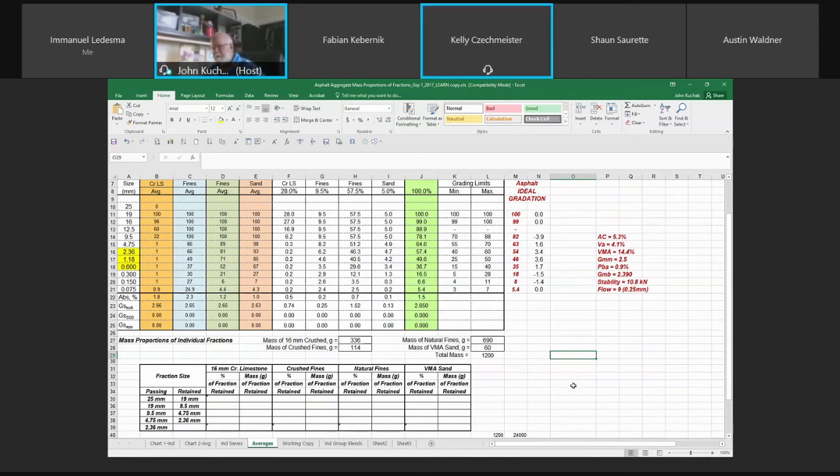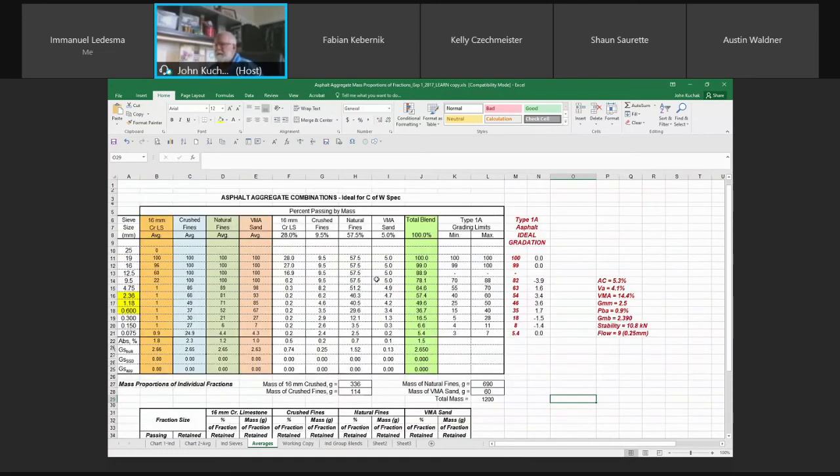Anyway, so it's okay for it to be tender if it's heavier loads, just not as frequent? Well, no, a tender mix, we say tender, it may not even compact well under the rollers. It fluffs. Oh, okay, so it could be both. A tender mix could mean that it can't take a load or it's prone to temperature increases. Like you were saying, if it's very, very hot, it's going to start to soften up quicker. Okay.